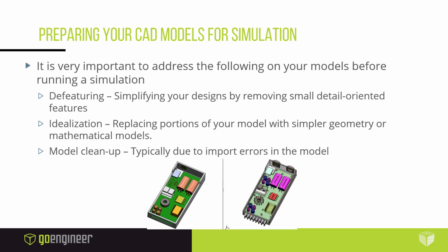Overall, if you fail to at least review your model for any of these items before starting your first project on your design, this can result in significant increased calculation time, problems with calculating internal volumes, meshing troubles, and just a higher probability of getting Flow Simulation errors and warnings in general.